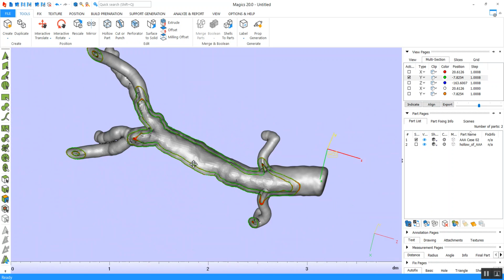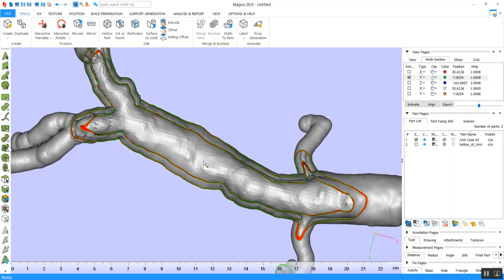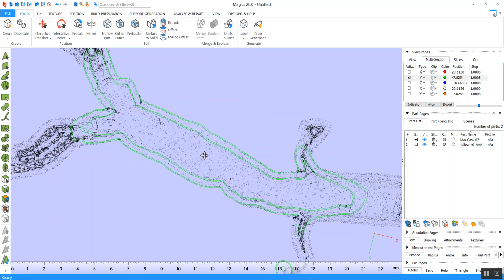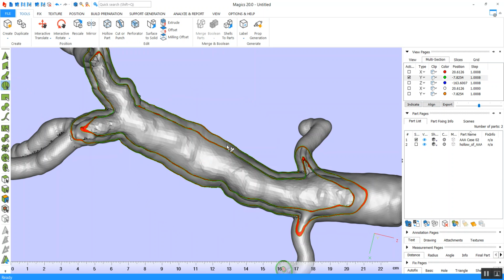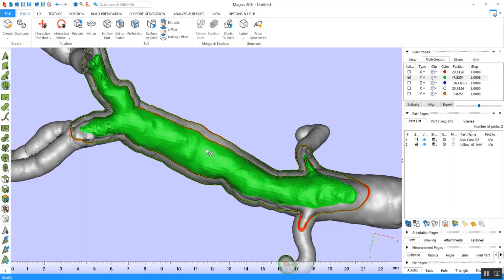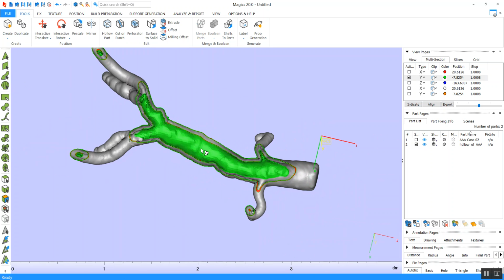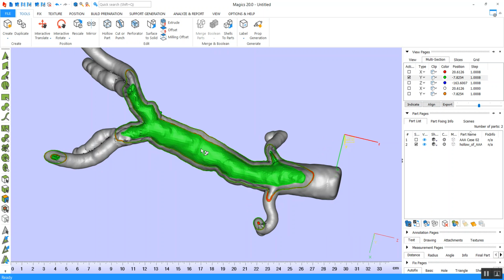And so you will also need to add some vents for draining resin out later, or draining any of your materials out. This internal cavity here, let me click on it. Hang on, nope, not selected. This internal cavity here will be full of resin if you are printing an SLA. And so you'll need to put some drain holes in there, both for cleaning the resin out and then flushing it with alcohol or any other solvents you'd like to use.